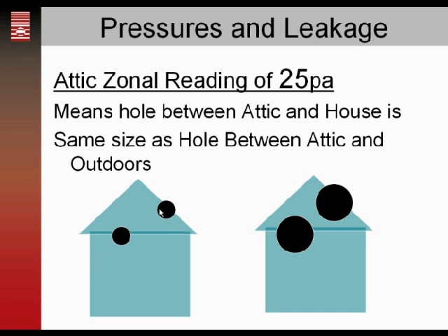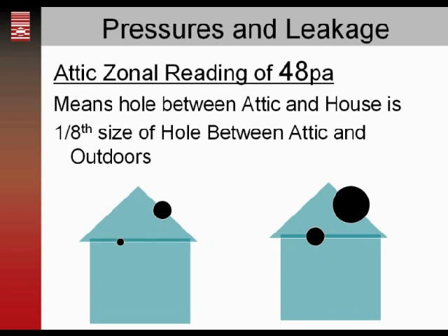So in that example I used, we could, in theory, even though we had all of those horrible bypasses we showed in the attic, we could add enough venting to get the zonal pressure numbers better. But by adding more leaks, you make your blower door numbers go up, and you make your energy costs go up.